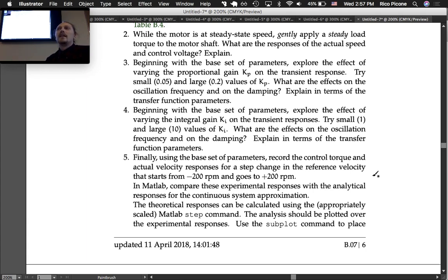So do you mean actual voltage response or velocity response? So we would convert it to a velocity response, but yeah. We would back out what the velocity response was, right? We actually measure voltage, but we typically run that through our conversion to speed and say this is our measurement, assuming this constant gain between voltage and velocity, which is pretty standard to do.